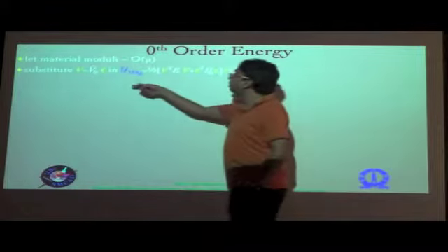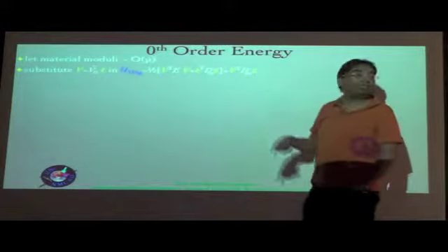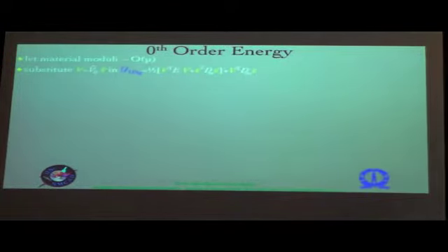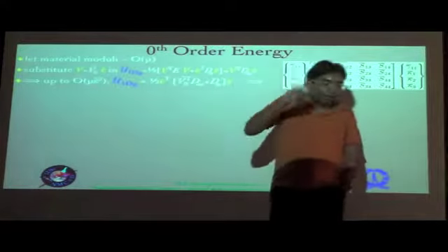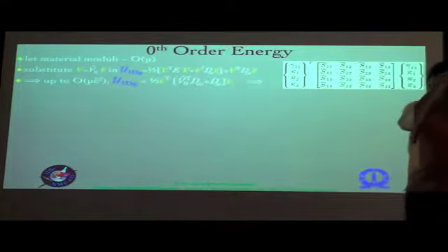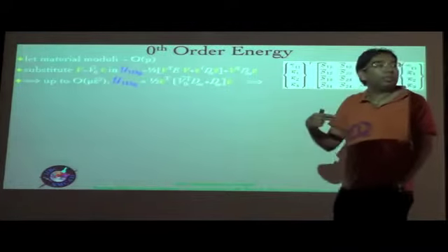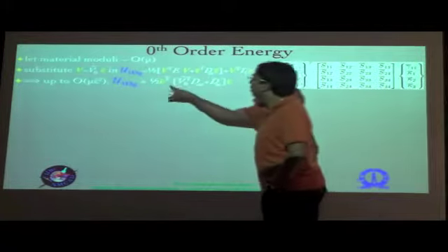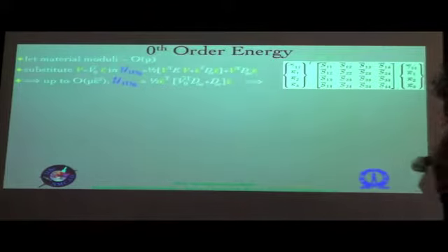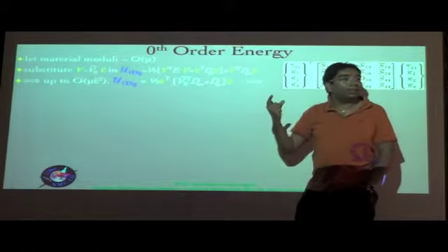When you substitute that into the expression that we have for U1D naught, which is basically this, and retain only the leading order terms, which is up to order mu times epsilon hat squared, you can see there is a parallel with the general case of the quadratic functional that we took for the variational asymptotic method minimization as well. Your U1D naught will basically boil down to this expression, and you see now that it is quadratic in the epsilon bars, as is expected.